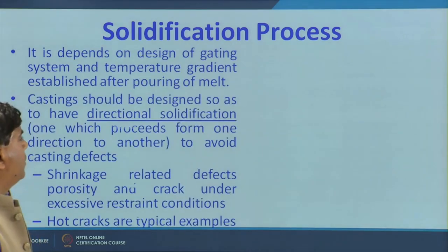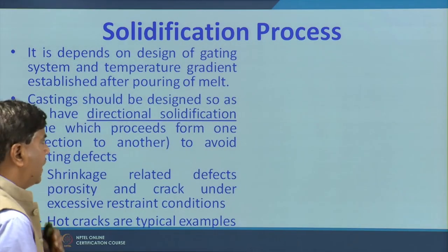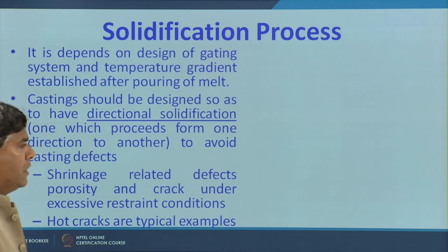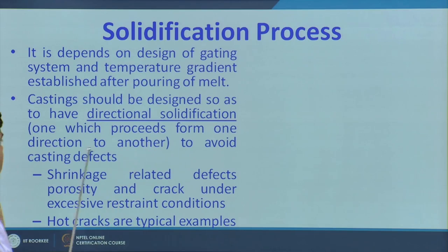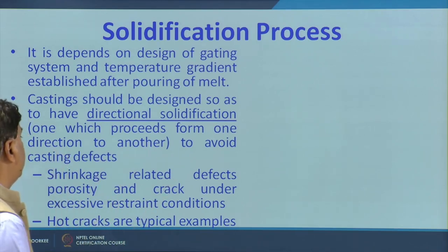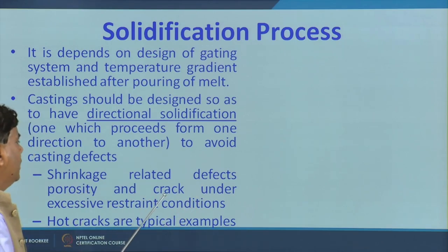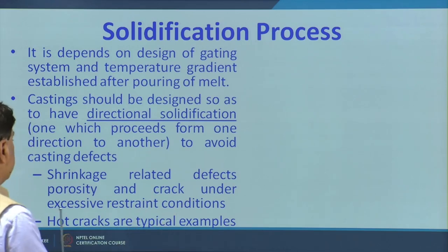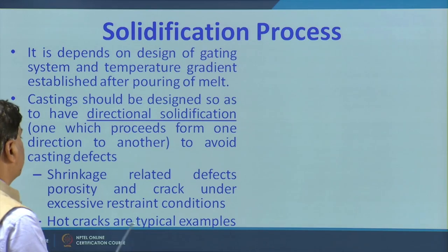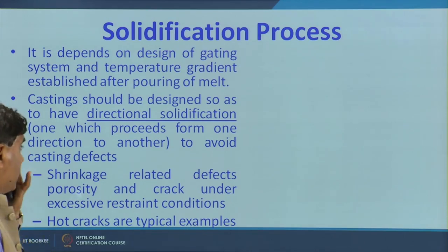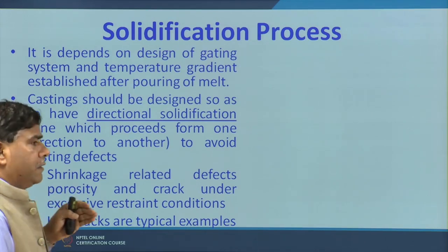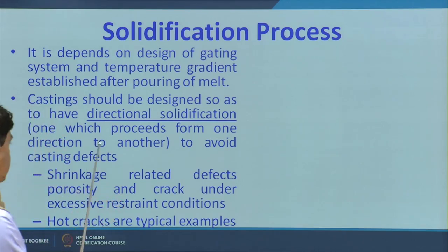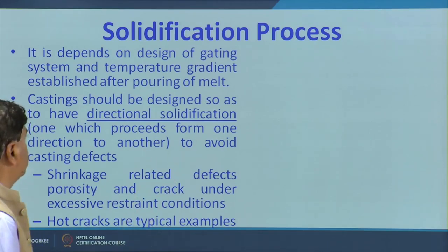We know that it is desired that directional solidification is achieved in the castings, wherein solidification starts from one end and completes at another end, so that the defects and the issues related with the shrinkage, such as the shrinkage cavity and the cracks under excessive restraint conditions, hard crackings are the typical examples which otherwise will be leading to a number of issues. So, when directional solidification is not achieved, these are the issues which are encountered.